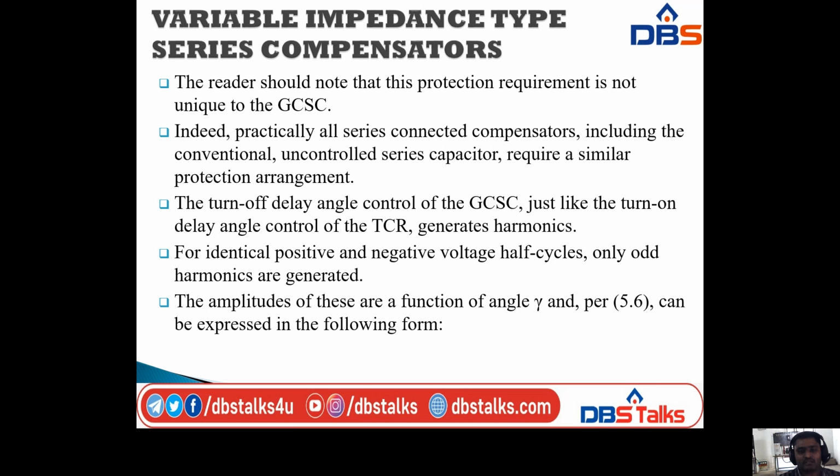The turn-off delay angle control of the GCSC, just like the turn-on delay angle control of the TCR, generates harmonics. Now we have discussed the main operation of the GCSC scheme, and now we discuss the harmonics. For identical positive and negative voltage half cycles, only odd harmonics are generated.